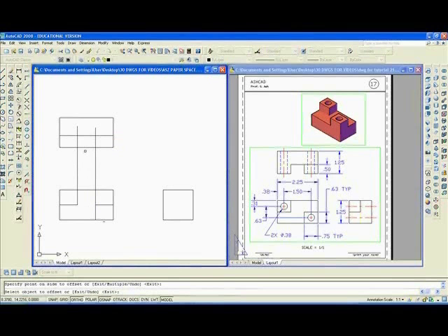And we'll break, BR, enter, that line. F for first, from here. Oh, I was on the offset command, so I'll undo that. Offset, enter, 0.5, enter. Fillet radius 0. You've got to keep watching the command line. Hit the space bar,